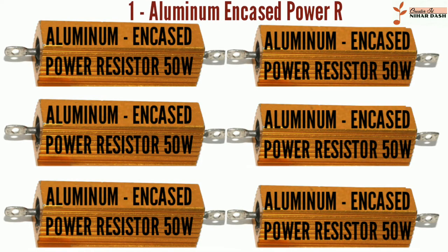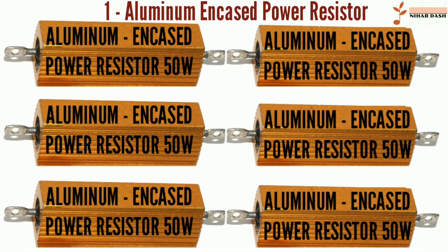Aluminum-housed power resistors are a preferred choice. Take, for instance, the pre-charge circuit of an electric vehicle or the surge protection system of medical equipment. The key requirement in these applications is quick heat dissipation during high-power operations. At the same time, the resistive element needs to be compact in size and maintain a relatively low surface temperature.